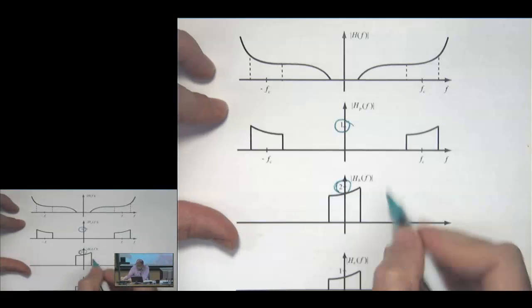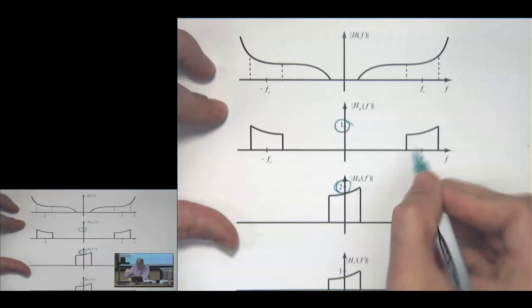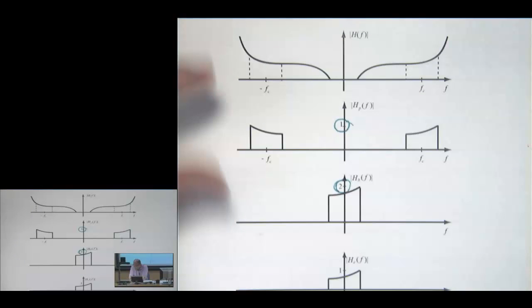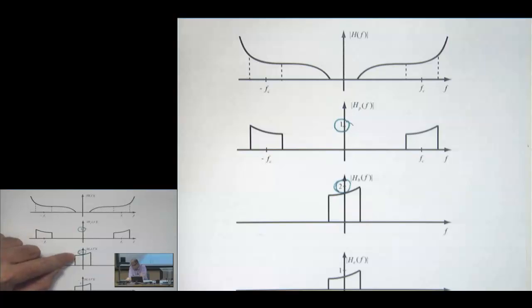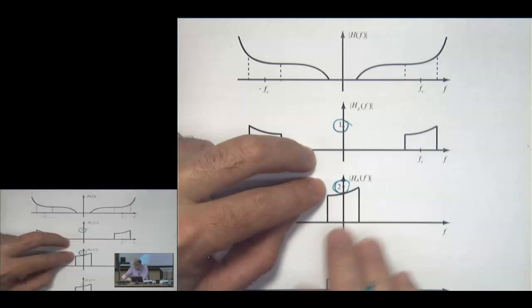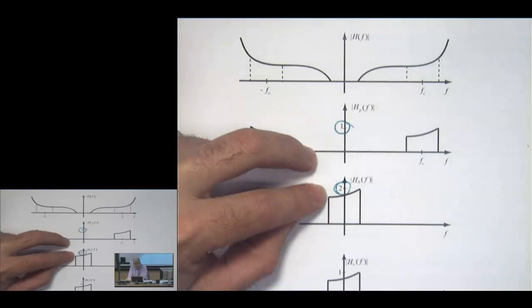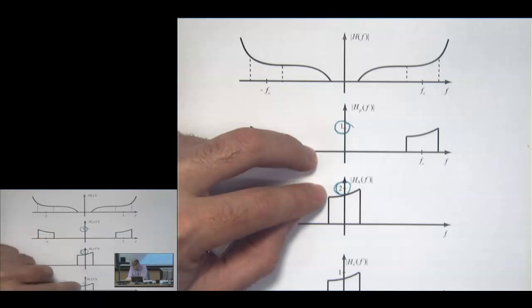And that comes because when we go from here to here, there's 1/2. So if we start here and go back, there's a factor of 2. Now the problem is that this factor of 2 would multiply our piece of the signal in that band, which we don't want, because that would screw up our signal power calculations. And so then we need to just divide by 2.